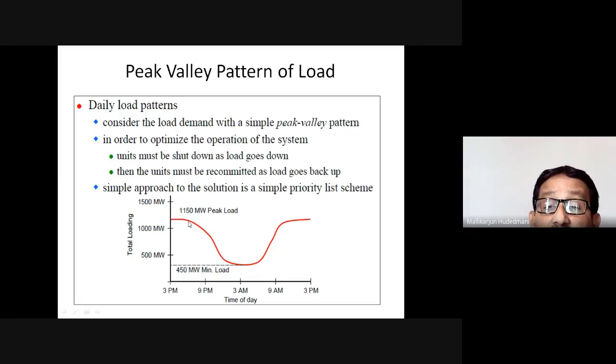In between the peak and base, intermediate load generators are able to switch, take up the load and remove it as and when load is falling. You can see here load is falling flat, again load is rising, peak. It is called a peak, valley and rising pattern of load. In this regard, certain generators of a plant are put in constant service. There is no impact of load variation on them. They deliver a certain megawatt continuously. We call them base load generators.